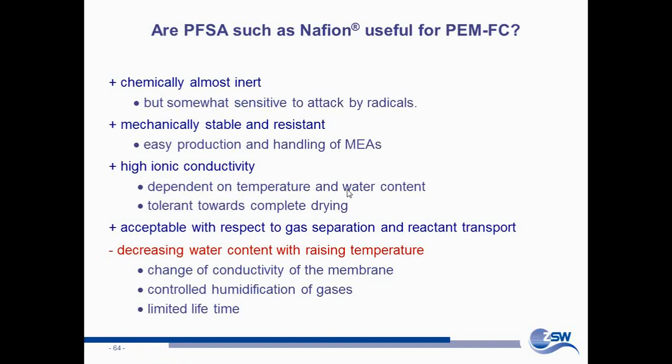So, the question is: are these perfluorinated sulfonic acids useful for the PEM fuel cell? Well, they're chemically almost inert, but somewhat sensitive to radical attack. They're mechanically stable and quite resistant. They make MEA production pretty easy, and handling of MEA is also pretty easy. They have good ionic conductivity, which obviously depends on temperature and water content.